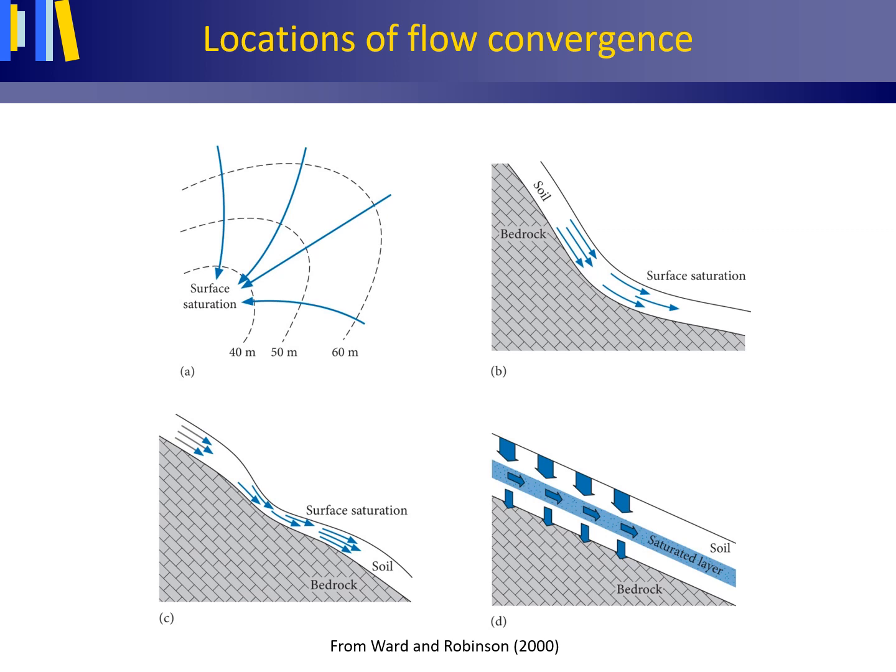Infiltration into a layered soil may lead to the development of a perched water table. Importantly for humid climates, when the perched water table reaches the land surface, any extra rain that falls will immediately become saturation excess overland flow, which is transported over land and thus rapidly to the stream, contributing to the quick flow of the stream.